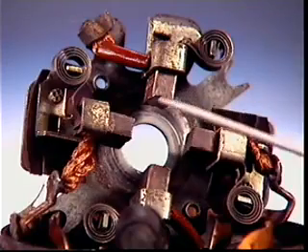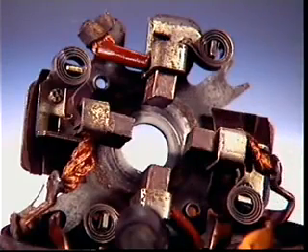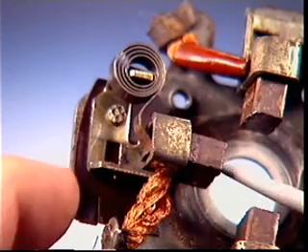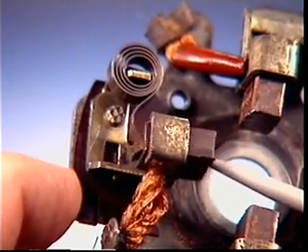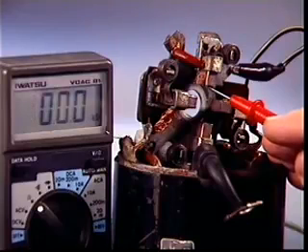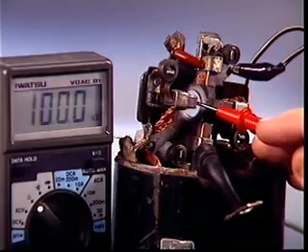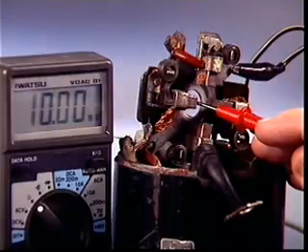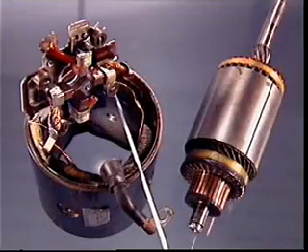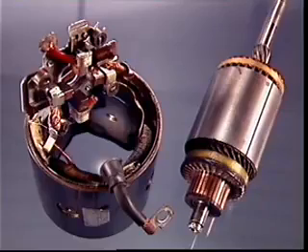The commutator end frame carries the copper-impregnated carbon brushes, which conduct current through the armature when it is being rotated in operation. The brushes are mounted in brush holders and are kept in contact with the commutator by tension spiral springs. Half of the brushes are connected directly to the end frame and via the ground return of the vehicle frame to the battery negative terminal. The other half are insulated from the end frame and connected to the positive battery terminal via the main starter solenoid input terminal. This can be a direct connection in the case of a permanent magnet type starter, or indirectly via the electromagnetic field poles of a series wound motor.